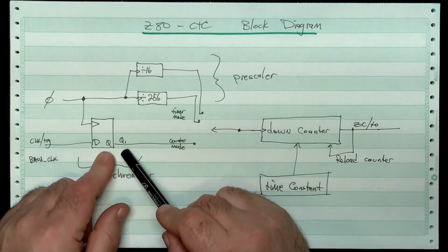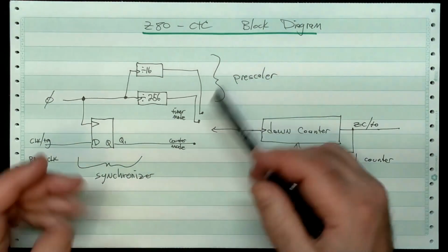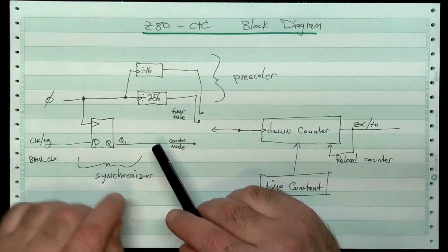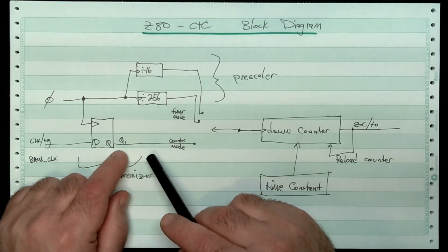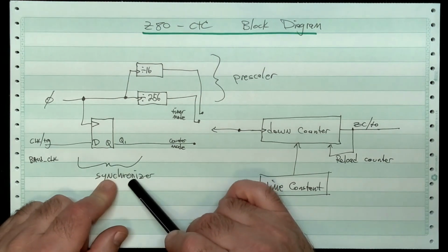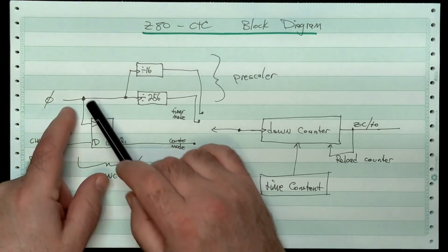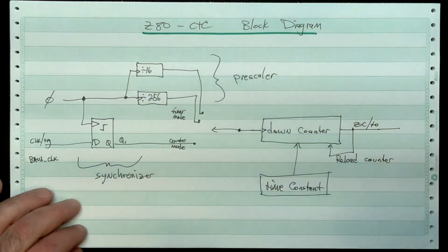This will work as well. It turns out the more of these you line up, the more you can overcome arcane, outrageous situations that in theory can arise. So this is a super simple synchronizer, all right? So the way this thing works is every time there's, let's say this is a leading edge, a triggered latch, okay?